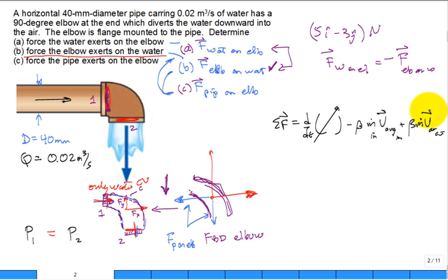Okay. So what are we going to put? For the force, we're going to have the pressure 1 times the area 1, the average pressure at surface 1 times area 1. And isn't that all in the I, and nothing in the J at 1? What about the surface 2? Isn't that going to be plus P2A2 all in the J? So really that's all your forces.